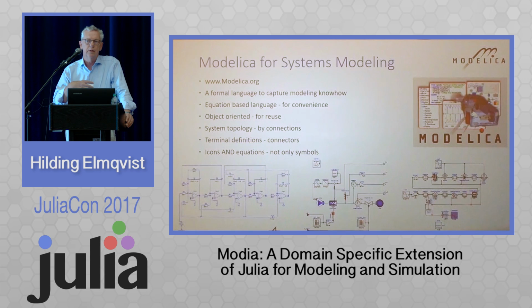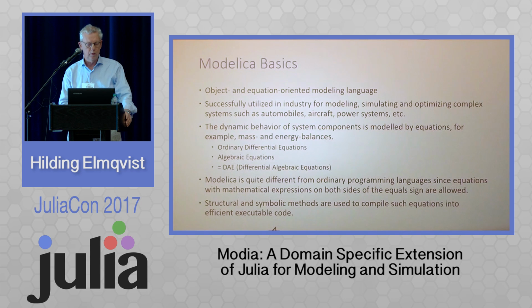And typically there is also an associated graphic. So you do these kind of diagrams, as you can see. An electrical circuit, for example, some fluid system or some gearboxes and rotational stuff. Okay, so this is the Modelica language. And the important thing is that it's ordinary differential equations and algebraic equations. These are what we're using. So usually called DAE, differential algebraic equations, which means that you cannot use just an ODE solver because there is a machinery that you need to implement to transform this DAE to a suitable form for evaluation.